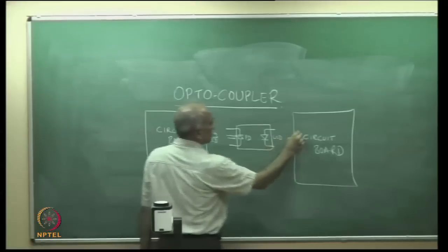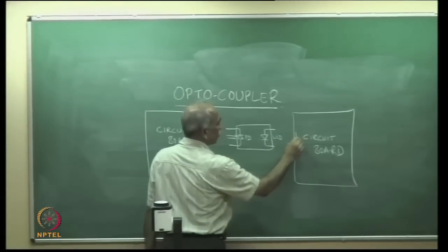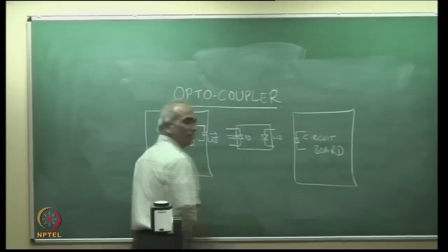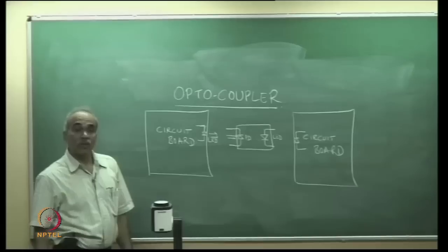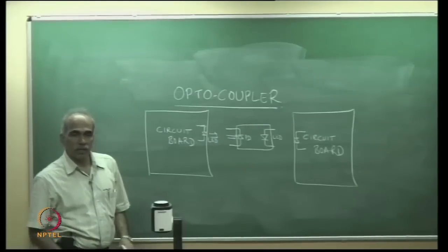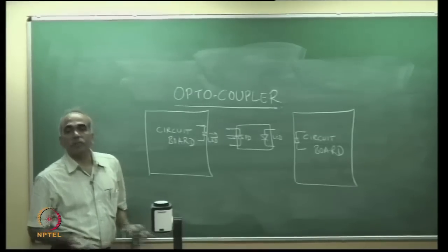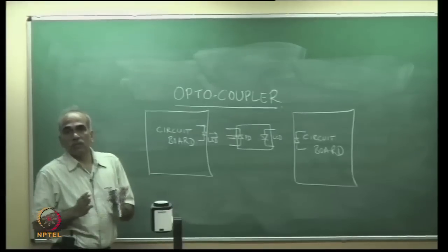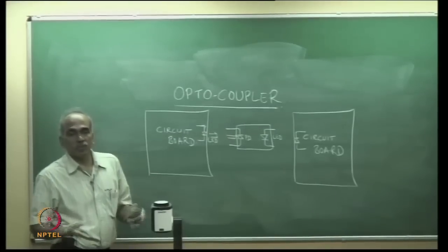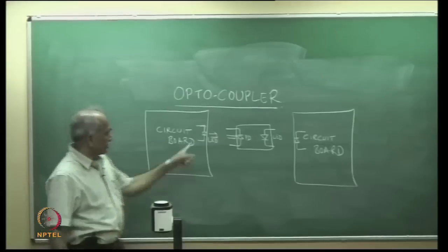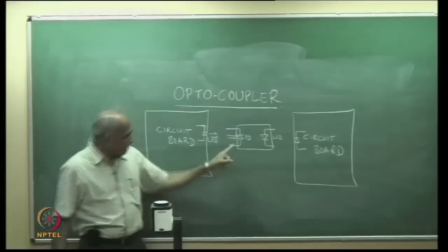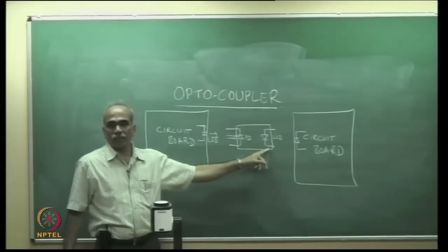There's a second photodetector on this circuit. This is just for historic reasons, but it has now come up again in a very big way for high density optical interconnects to connect chips which are dealing with gigabits of data. So this was the early use of an optocoupler which had one photodetector and a light emitting diode.